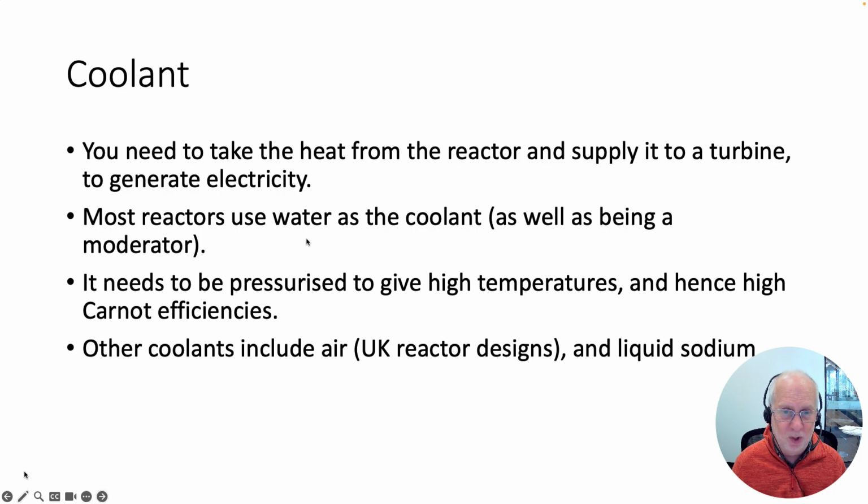It's a benefit of using water. It can act both as a moderator and as a coolant. It needs to be pressurized to give high temperatures though. I mean, if you just bring it up to the boiling point at 100 degrees, it's going to give you a low Carnot efficiency. So normally the water we put under enormous pressure so that it can boil at a much higher temperature so you can get more of the energy out.